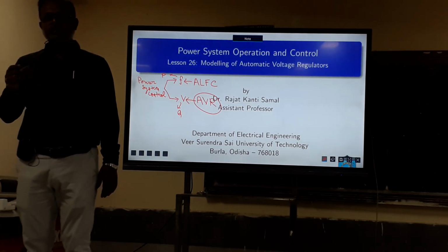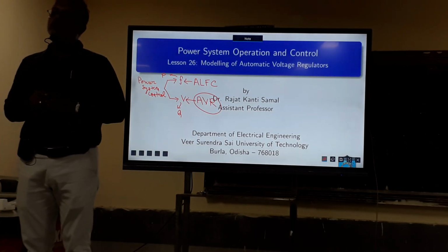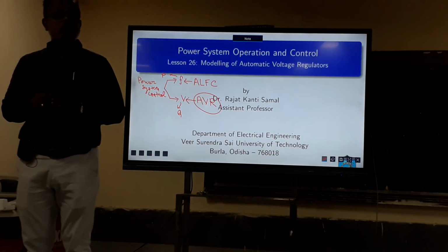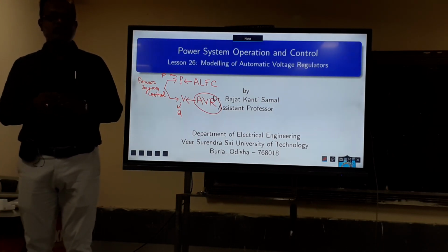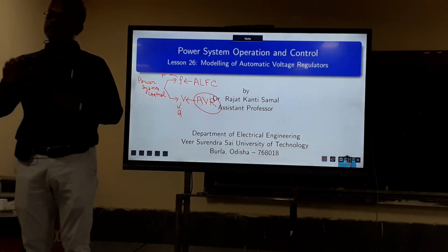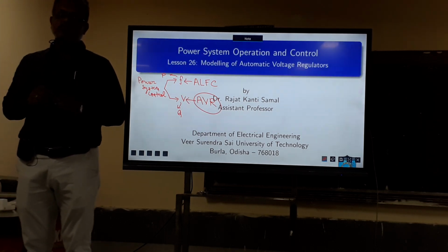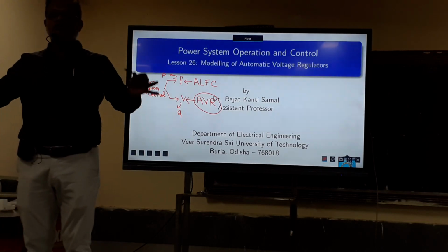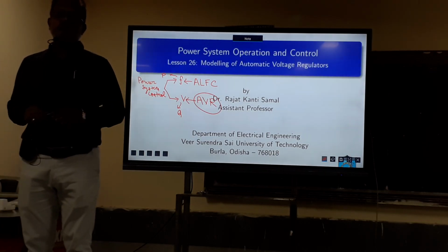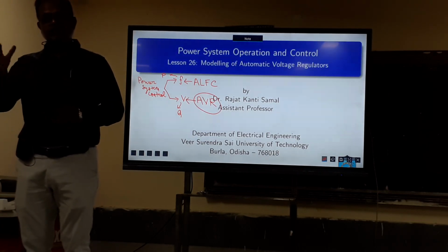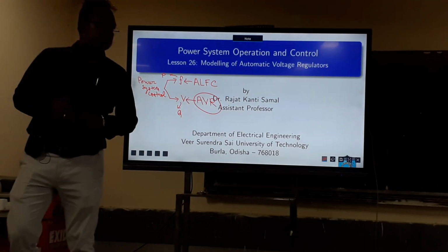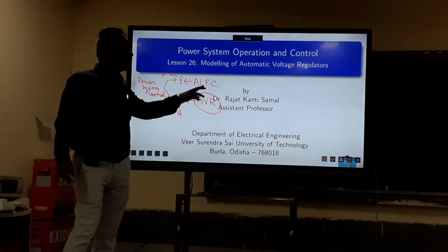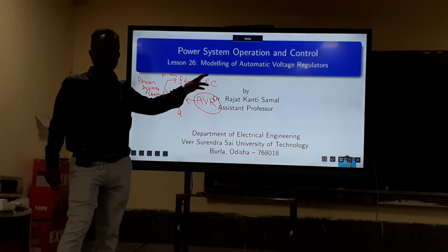So voltage regulation happens, and also I have told you voltage regulation is generally a local phenomenon rather than a system-wide phenomenon. So it is controlled at the distribution level. There is no need for the generator to always save the power system from low voltage. There are other means. So this is a small part of it, and we will devote only one class to this.